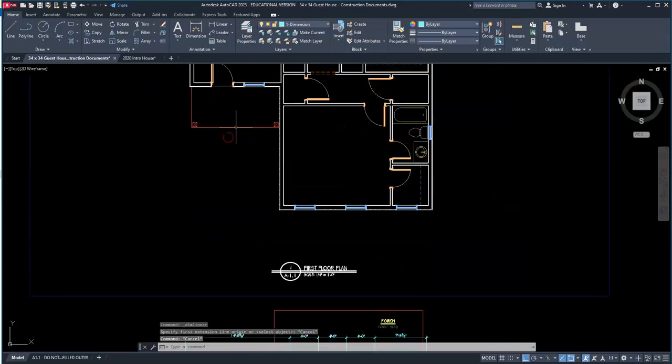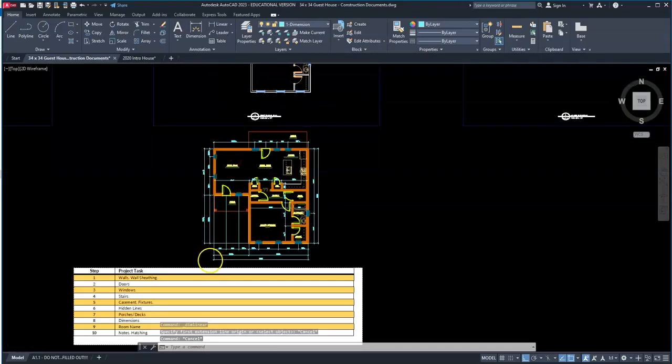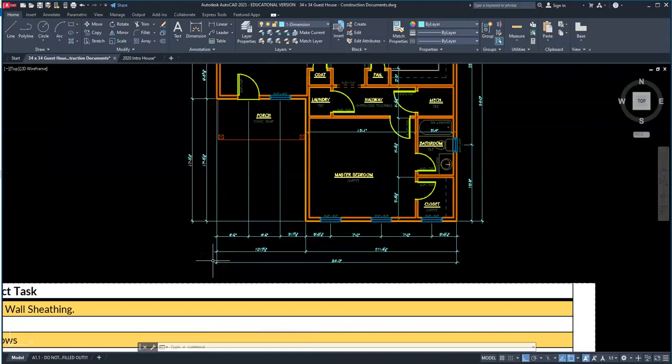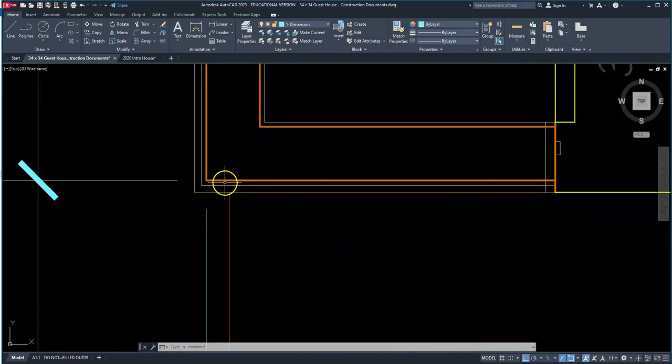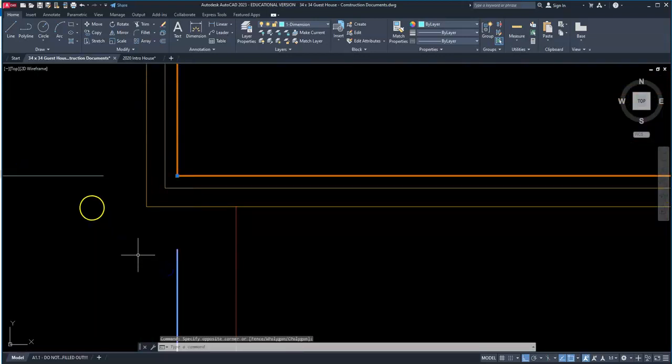The reason for this is when you're framing a home, the plywood and the outside siding is not there at that current time. So we need numbers that show from the stud lines. So you'll see here in the final example, all of the dimensions are selected on the stud. So if it helps you to turn these lines off, please do.